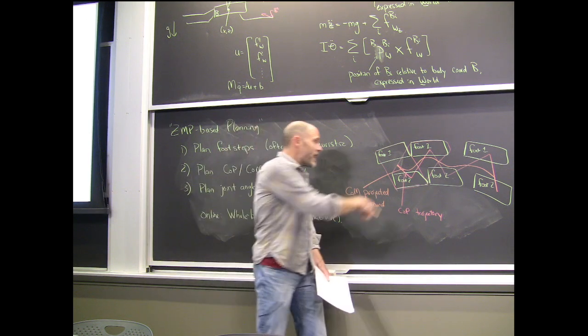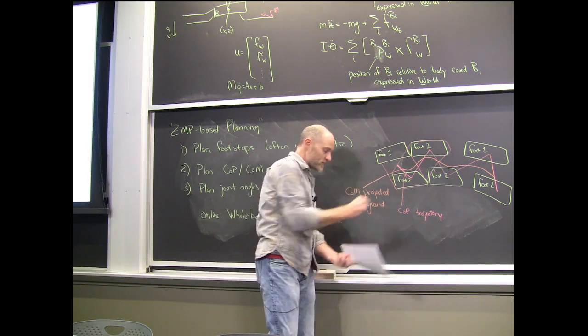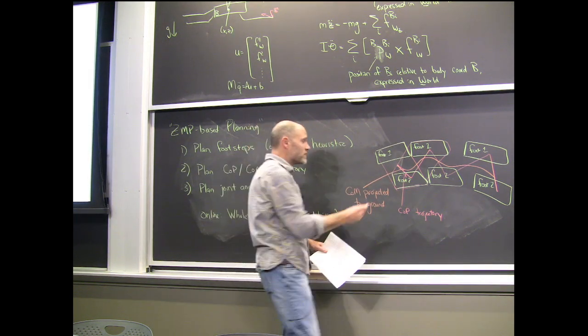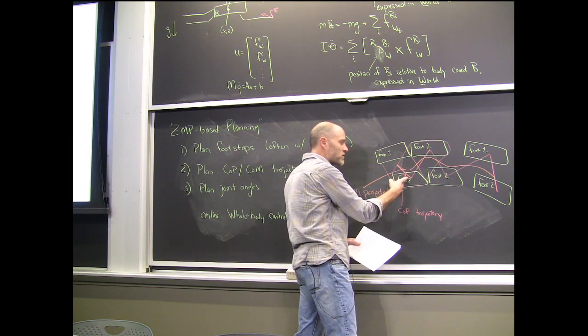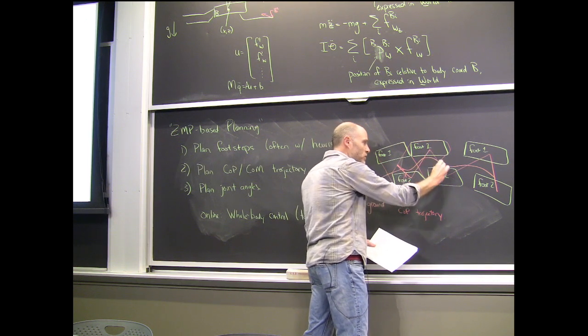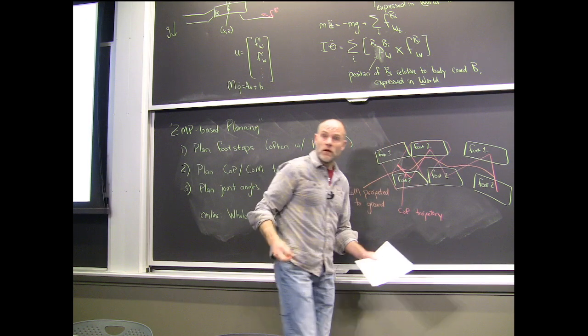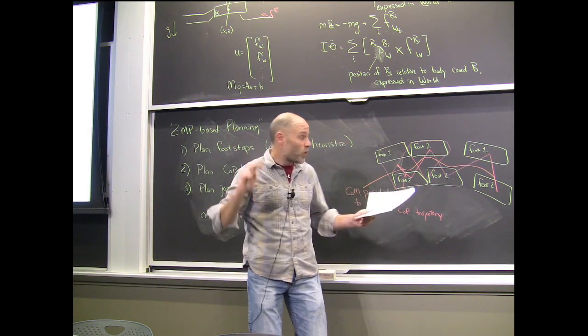And what's interesting, the timing really matters, okay? So if you were to make the thing slow, if you move very slowly, then the accelerations will be small. The difference between the center of pressure and the center of mass will be minimal, and you'll come close to following. Your center of mass will stay largely over your ZMP, and you can be a static walker.